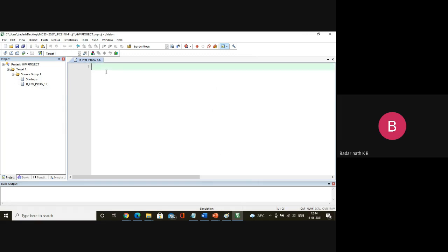Now, as we start writing the program, how do we write it? In a C program, we say int main. Then we execute the required logic. As we know, what was the last instruction we were writing in assembly? Yes, jump. We were writing B. In the assembly language, if you remember, we were always writing an instruction like B skip. That means after executing all the logic, we keep executing indefinitely at the end of the program, because there is no OS.